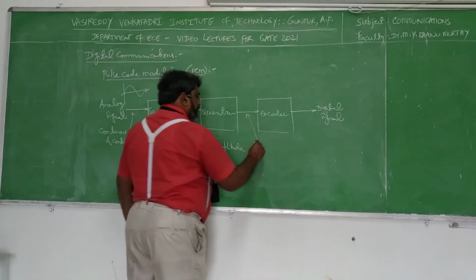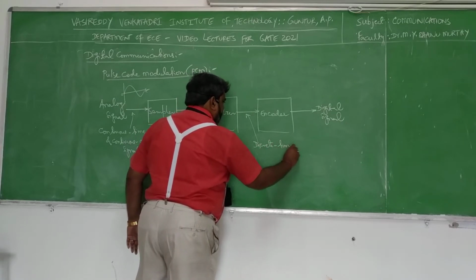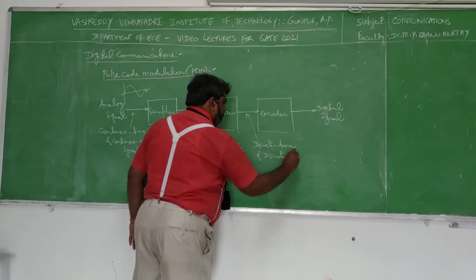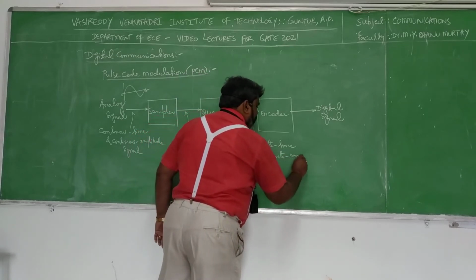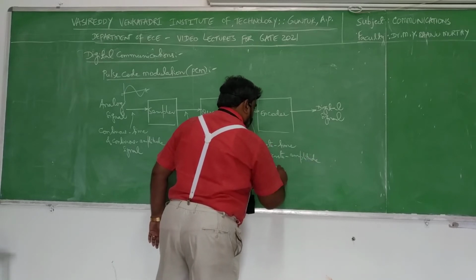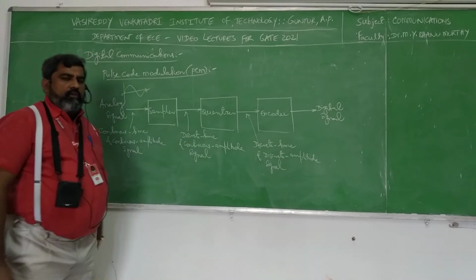So, the output of the quantizer: time is discrete. For simplicity I just put it as discrete time, and the main difference comes here. The amplitudes are now converted into discrete. So it is a discrete time and discrete amplitude signal. Both time and amplitude are now discrete.